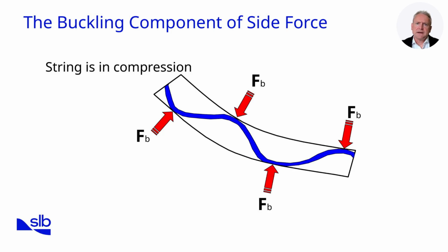At the onset of buckling, the first order buckling limit is referred to as sinusoidal buckling. The drill string begins to form a sinusoidal or snaky shape on the low side of the wellbore. If the compression continues to increase beyond sinusoidal limits, then at a certain point, helical buckling begins, resulting in spiraling of the drill string around the borehole, causing lockup, as described in coiled tubing drilling, with high side forces and infinite contact points with the wellbore.